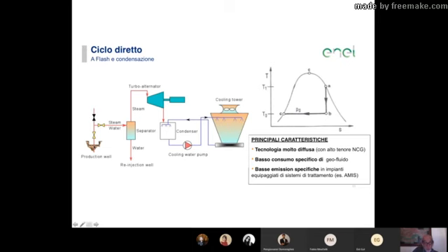water with many bubbles in. You need water with some bubbles in so you can drive the fluid all the way to the surface, because water with bubbles is less dense than simple water. So while at the surface, in the separator, you flash this water plus bubble into steam plus a water phase that you send to reinjection, or you send to a binary power plant, and we'll talk about this later.